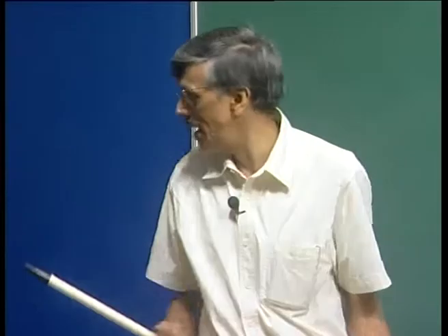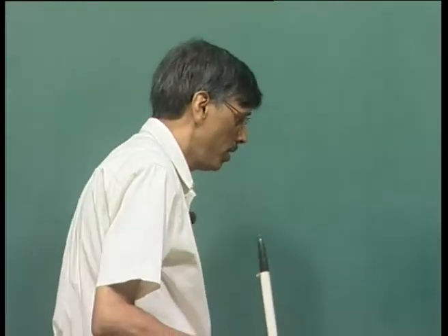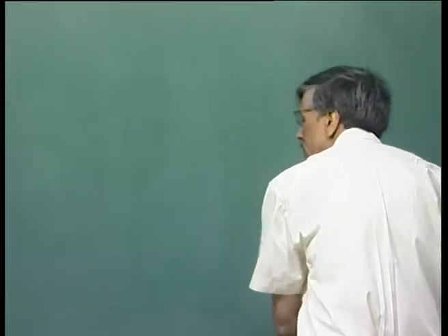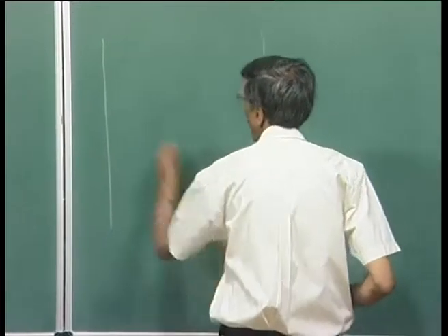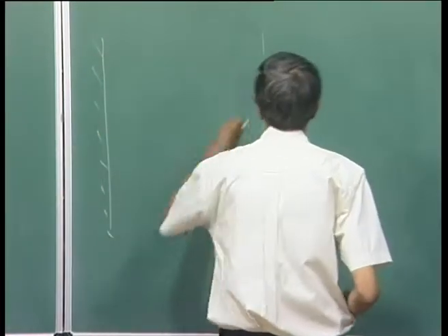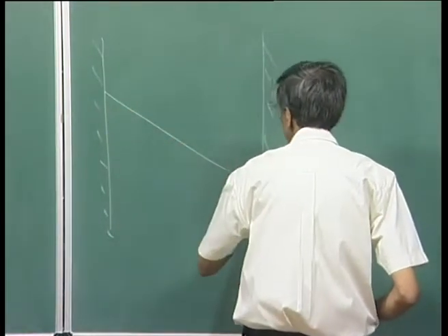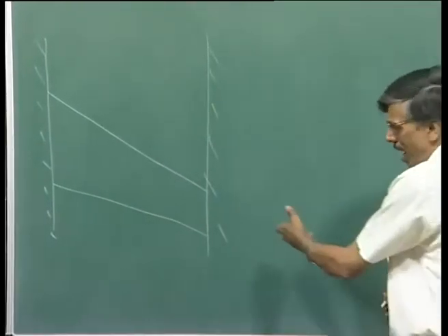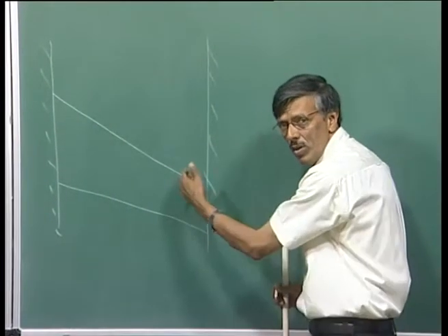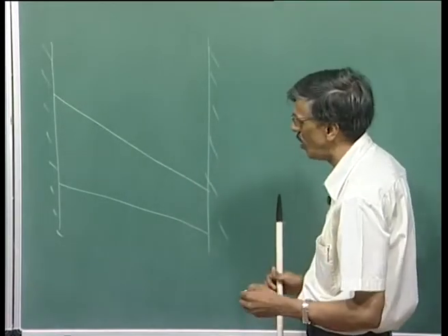So, since that is the flow direction, we call that itself u, and it has no other component. And when this problem that I was telling you about is performed experimentally, what you end up doing is you have, let us say, a wind tunnel wall like this, and you fit in a kind of swept wing which will connect from wall to wall. The idea is not to have any of the stiff vortices which will affect the flow in the near vicinity, but you do it in a wall to wall fashion.